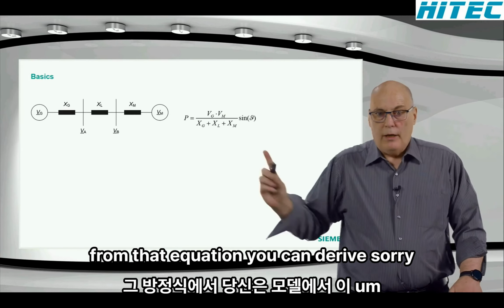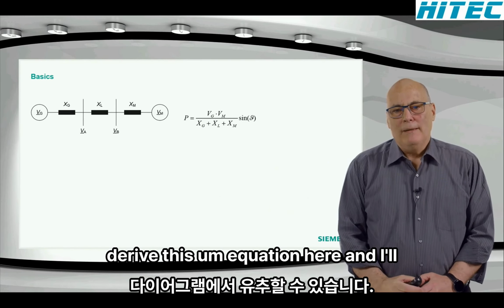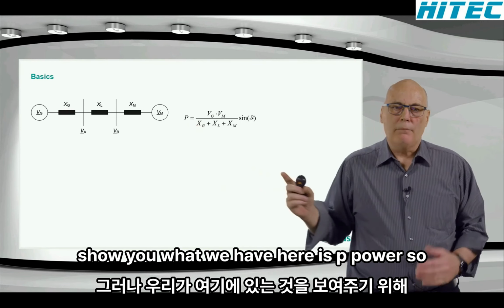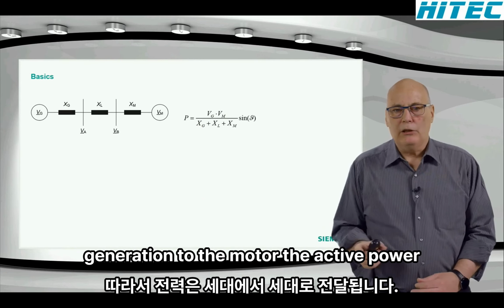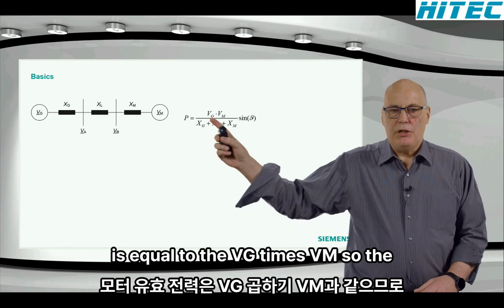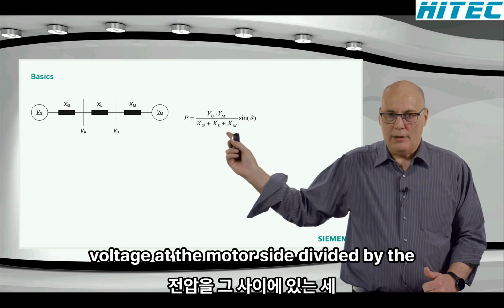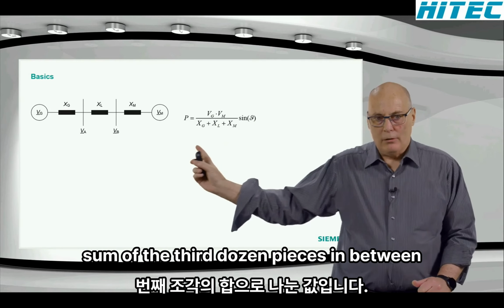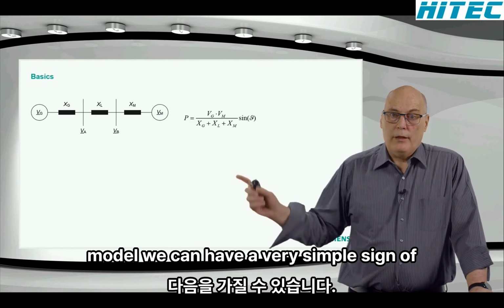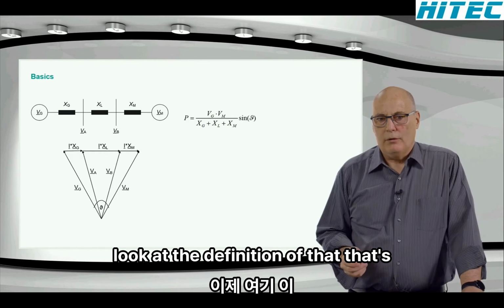From that diagram, that model, you can derive this equation here. I'll show that in a graphic form, but just to show you what we have here is P, power. So the power transferred from the generation to the motor, the active power, is equal to VG times VM, the voltage at the generator side and the voltage at the motor side, divided by the sum of those impedances in between. And because we're using this lossless model, we can have a very simple sine of the angle between them. So let's have a look at the definition of that.